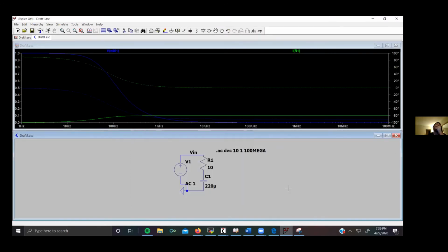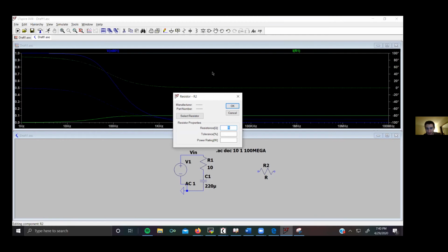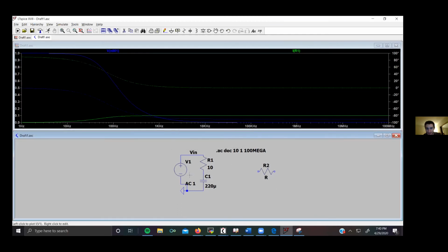Yeah, so here, I'll go back to my screen. I'll take a resistor. I have it where I'm able to move around. For me, it's Control R. I'm not sure if there's another shortcut for it though. Otherwise, when you place it, I believe there's an option to rotate components. So you have to actually pick it up first. Yes, if you want to pick something up, you can hit the move or the grab. Oh, okay. So move, Control R.